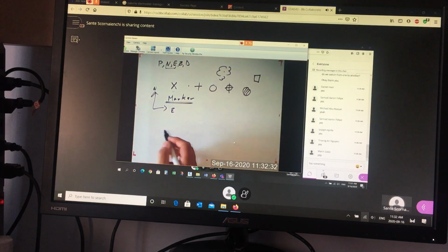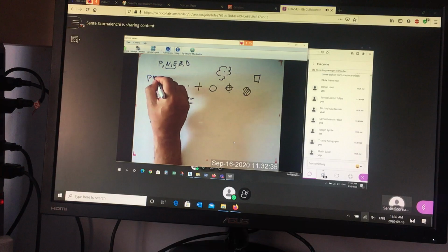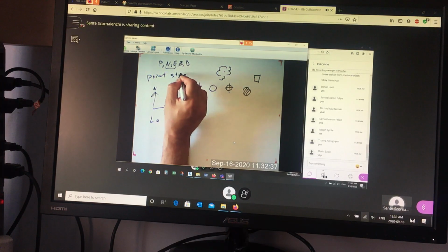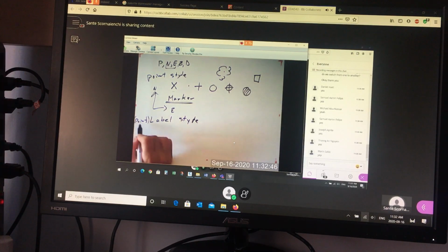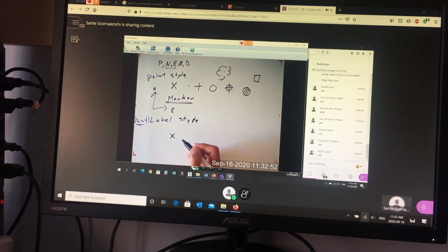The other thing we look at is the label style. So this is the point style. This is the label style. And sometimes called the point label style. Sometimes they drop the word point, but label style for the point. What does that mean? Well, once you mark the spot with the marker, then you can annotate it. The classic, the basic one you'll always see is a label that shows three things. The point number, the elevation, and the description. This is classic surveying information.